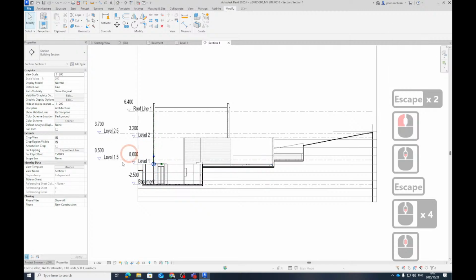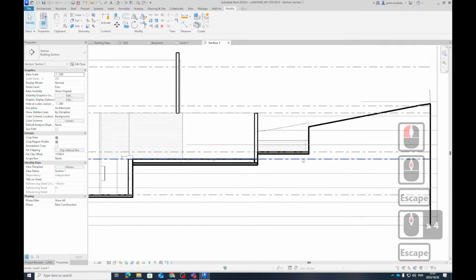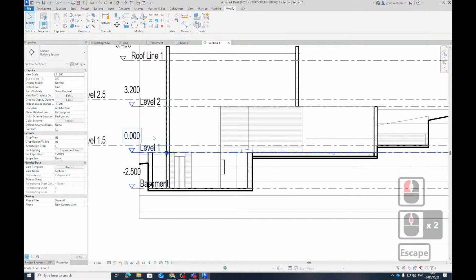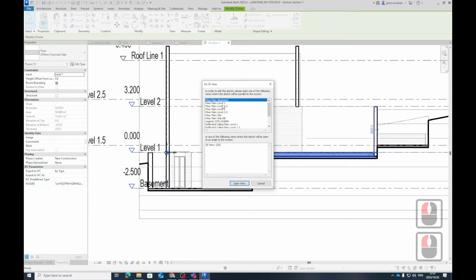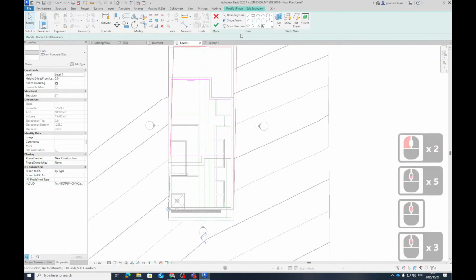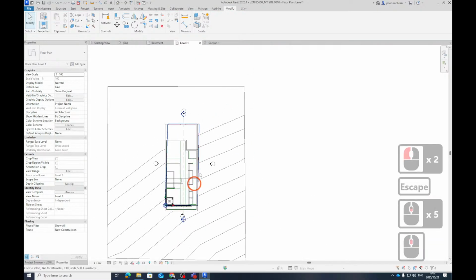Okay, so just make sure that you try and get rid of these, move objects to the cross. Now you can change these floor slabs to work because maybe this must go across there. Maybe the basement, maybe it is closed. Yeah, it is closed. So maybe this floor slab then. But I will tweak the floor slab because there's different levels in my thing. But now you understand that every floor slab, everything that you create is always going to work by reference. So on plan, walls, floors, roofs, they're all referencing a level.